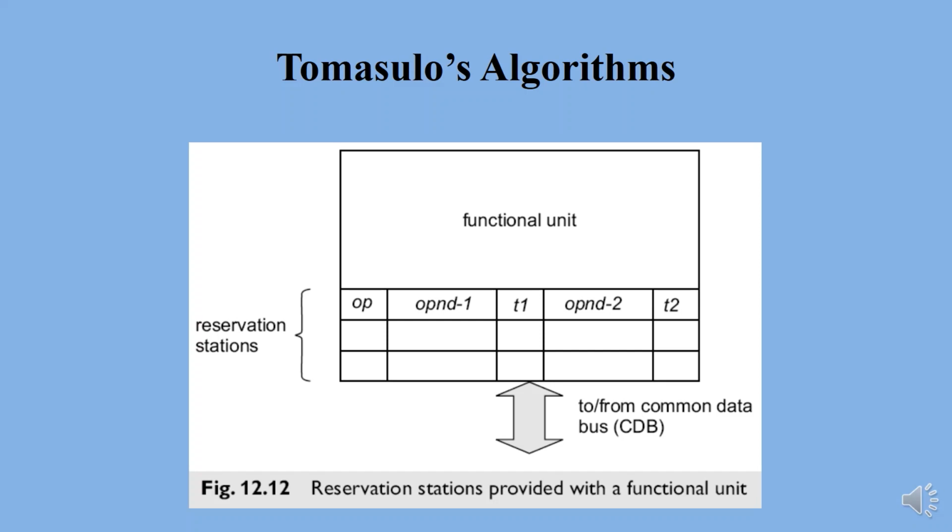Thus, operand forwarding is achieved here with the use of tags. All the destinations which require a data value receive it in the same clock cycle over the common data bus by matching their stored operand tags with the source tag sent out over the bus.